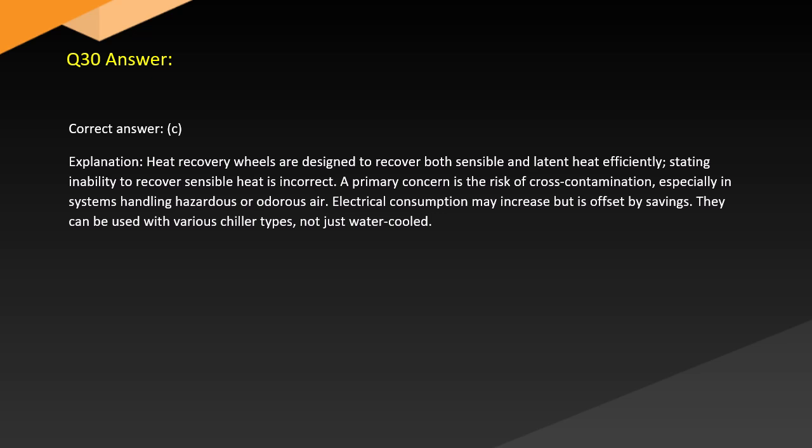Answer. Correct answer: C. Explanation. Heat recovery wheels are designed to recover both sensible and latent heat efficiently. Stating inability to recover sensible heat is incorrect. A primary concern is the risk of cross-contamination, especially in systems handling hazardous or odorous air. Electrical consumption may increase but is offset by savings. They can be used with various chiller types, not just water-cooled.